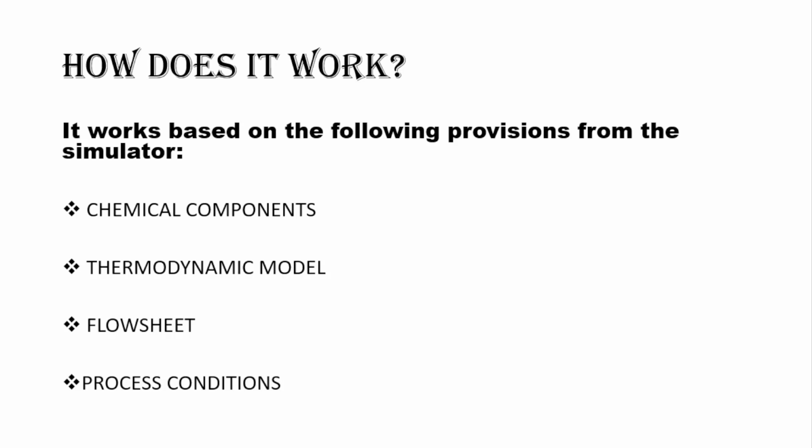How hot is your water? What's the temperature? Or how cold is it? What is the pressure? What is the flow rate of the water that you say is coming in? So you have to provide that. And if you are using a mixer, is there a pressure drop within the mixer? At what pressure does the tank exist? So you have to show all of them. That will be the process condition. It's not something difficult.